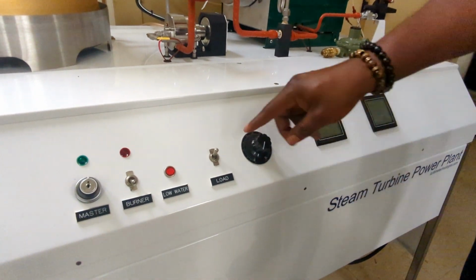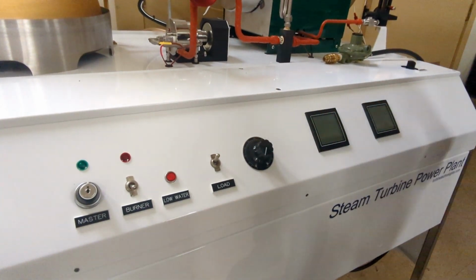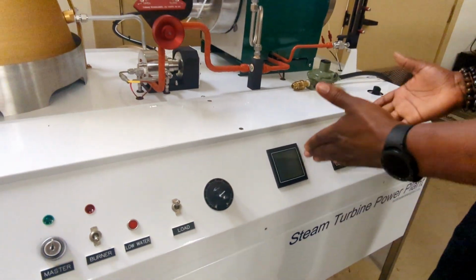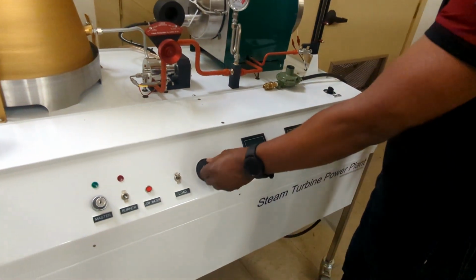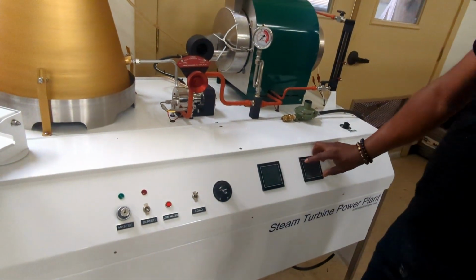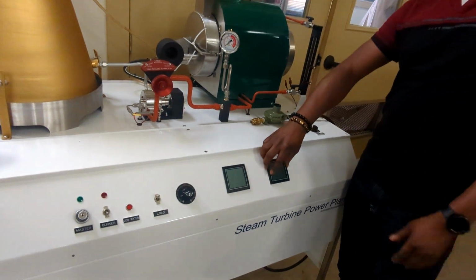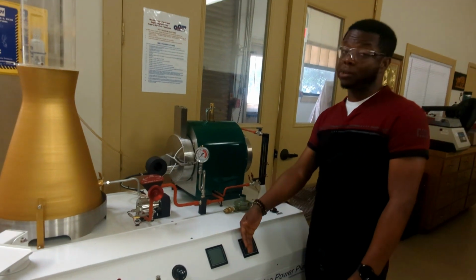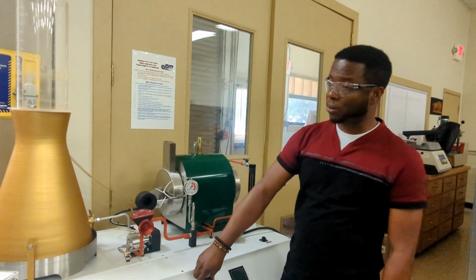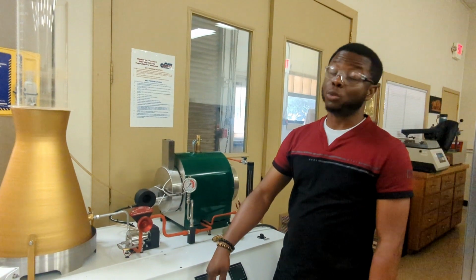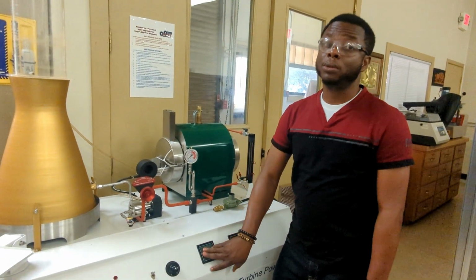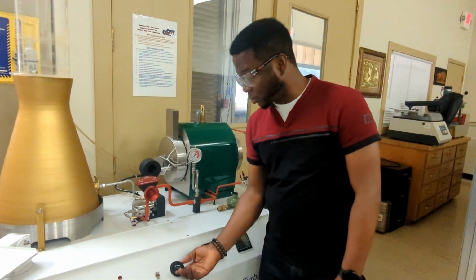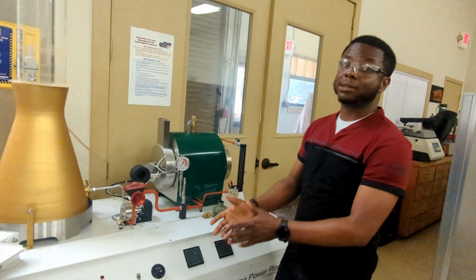When we switch up our load, we use the load rheostat. This is the load rheostat to monitor the amperage and the voltage of this steam turbine power plant. We can use this to regulate, and over here we need to get within the range of 6.6 volts at this voltage regulator. You can also monitor from 1 amp to 2.2 amps. This will give you the current and this will give you the voltage. You use this to regulate. It shouldn't exceed that range.